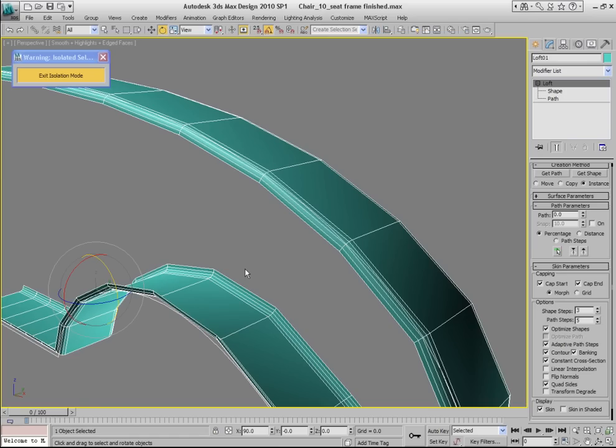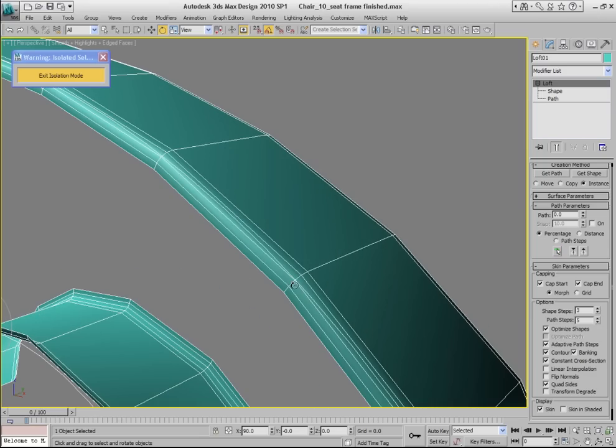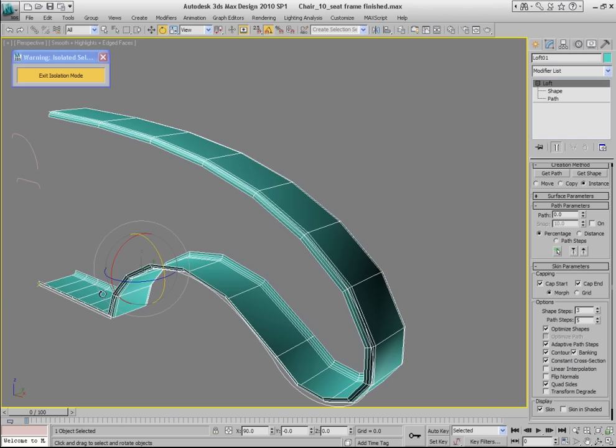But here for the front fillet, we want to have more edges built into this curvature of this fillet. The reason why is because we're going to create a transition from the small radius into the large radius, and the loft object will do a little better job if the number of segments for the large radius and for the small radius would be the same. So obviously if I increase these parameters right here, it will increase the number of segments dividing those radiuses everywhere in this object, but we only want it to be applied to this specific edge.